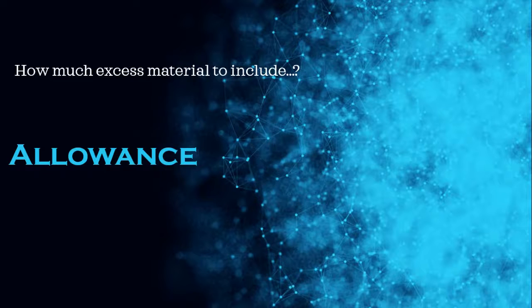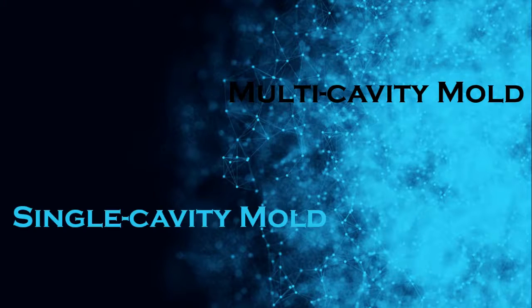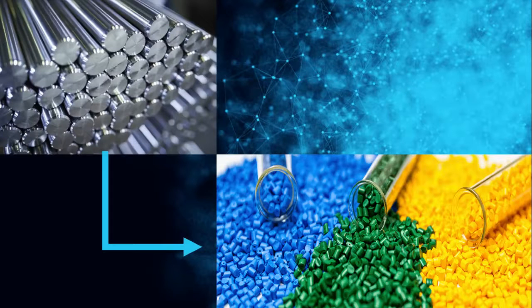After knowing this, we can think about designing a high volume process for these parts. For the engine airfoils, I would think of a multi-cavity mold because the pieces aren't so big and we could make more of them at the same time. But for the nozzle guide vanes, a single cavity mold would be better because it's a bigger piece.